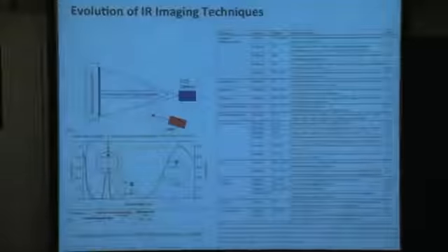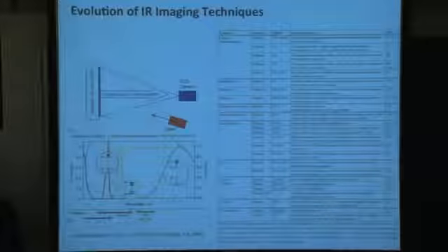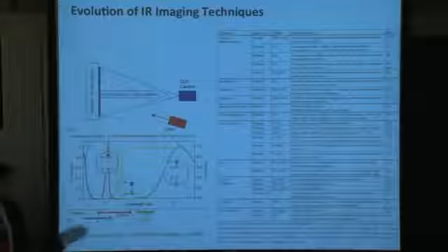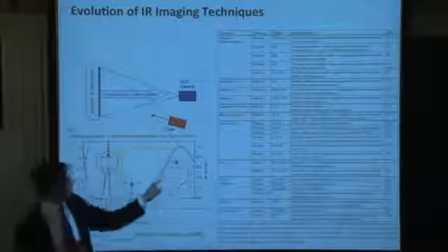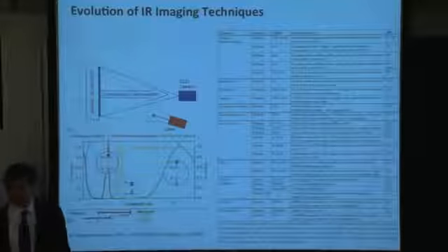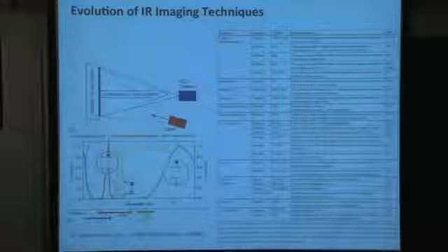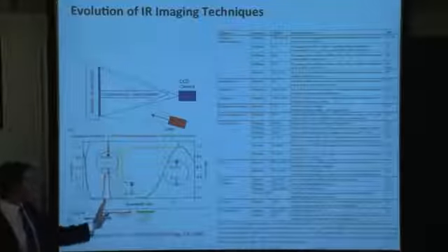This is wavelength. This is intensity. This is the emission spectrum of a solar cell. So if you were to measure what color light a solar cell emits after you pump current into it, this is more or less the spectrum. So we have the thermal radiation shown over here. This is longer wavelength light. That's the heat that it gives off. That's what indicates current flow inside of the device. There's the band-to-band luminescence right here. And we'll neglect the other two for now. Those are more advanced concepts.